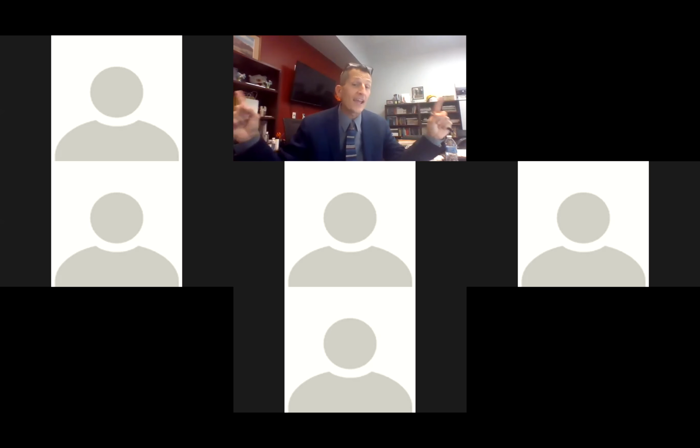The 2 at the end, let's define what the ends are. One end, Ms. Sale helped us with that end. That end comes from the fuse panel or your breaker panel, whatever it is. That's where the power comes from. That goes into a 3-way. The other end, the one that goes directly to the light bulb, that's a 3-way. Both of those are 3-ways. Everything you use in between is a 4-way.